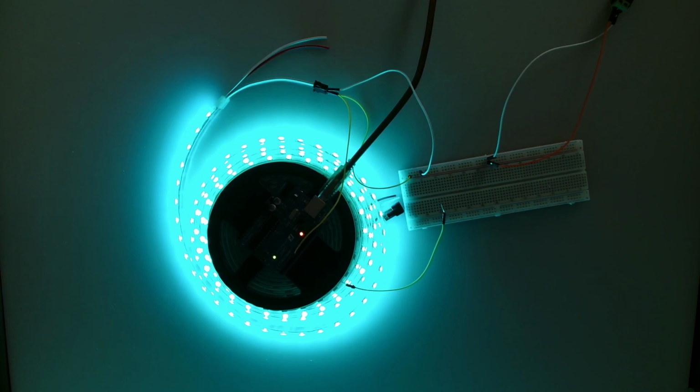With all electronics projects, the thing that we get wrong the most often is common grounds. If you don't have a common ground, you will have totally wacky errors. And we've set these LEDs up with an external power supply to just show you what that looks like.